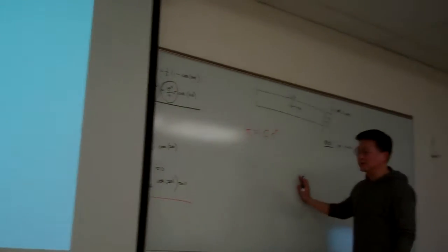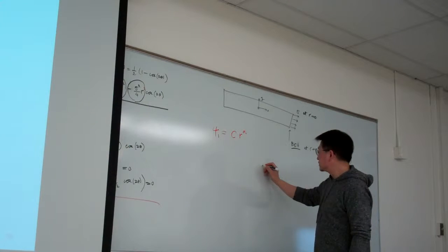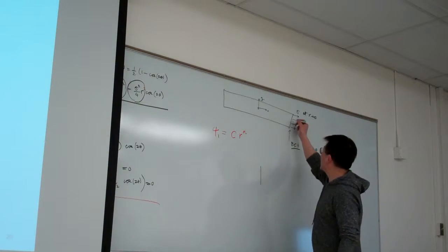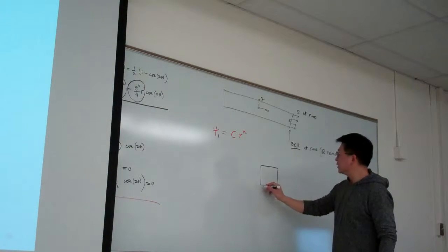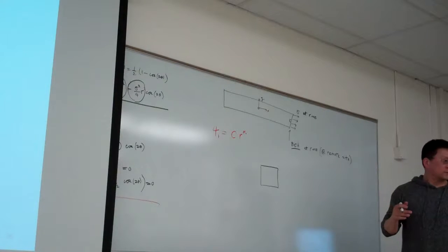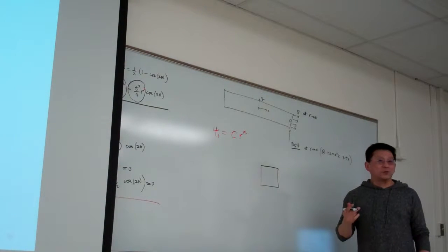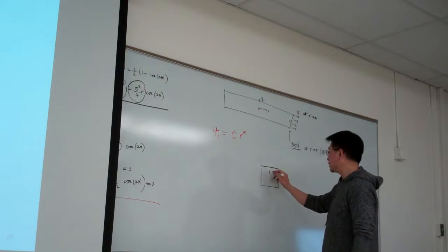How to convert? If you remember, let me take a small element here. We can apply the transformation of the stress using the two-dimensional Mohr circle, or using a formula. Let me remind you what we did before.